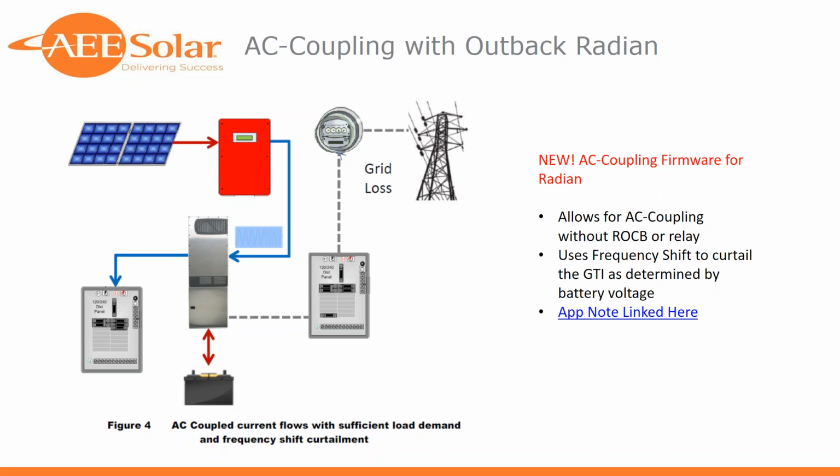Well, we know that grid tie inverters require a qualified grid to be able to export power. This goes back to UL 1741 and now UL 1741 SA. A grid tie inverter needs to see a qualified grid, and count up over a 5-minute period to make sure the grid is qualified before it is allowed to harvest wattage and produce AC power. Why is that? It goes back to the original intent of protecting line workers. If there was an outage in a given area, be it planned for service or unplanned, electrical workers could service that grid knowing that the grid was down. It's similar to your lockout tagout procedures for servicing equipment. So if that grid-tied inverter does not see a qualified grid, there is no production.